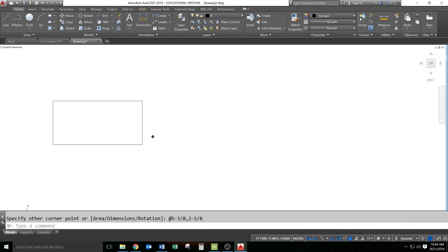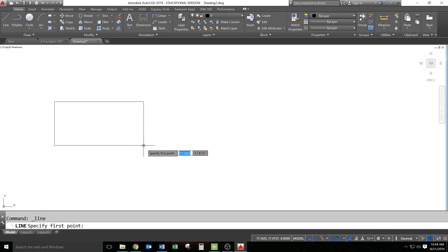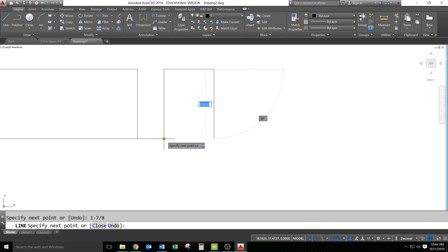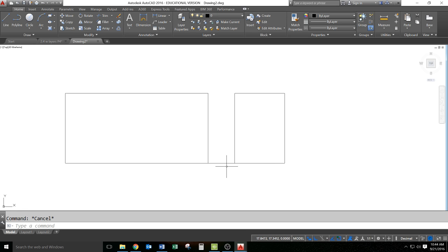I'm going to just block it out, and now I'm going to draw the right side view. When I draw the right side view, I want the space between to be 1 inch. So I'm just going to draw a line off of here that's 1 inch apart. So that's how far my views are going to be spaced apart. And remember, my right side view is going to have the exact same height. So I can put my mouse right there and just let it sit there for a second, and you'll see this little green line. Now I can click, and I remember that my depth is 1 7/8. So 1-7 divided by 8. Hit enter, and I just bring this down, hold my mouse there for a second, and there it is, and I close my rectangle. And now that I'm done with this, I can delete this line right here, and there's my front view and my right view blocked out.